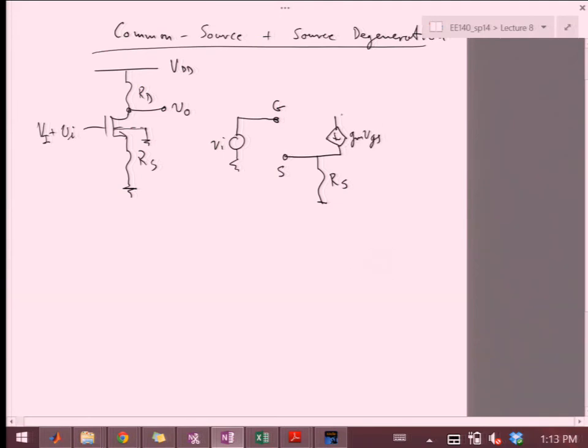And then I have gm·VGS, a current source, and in the opposite direction, gmb·VSB. R0, and then I'll have the RD to ground, just because the DC supply is a small signal ground. This is VGS, and this is the body, this is VSB.